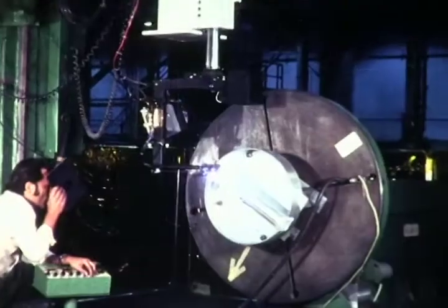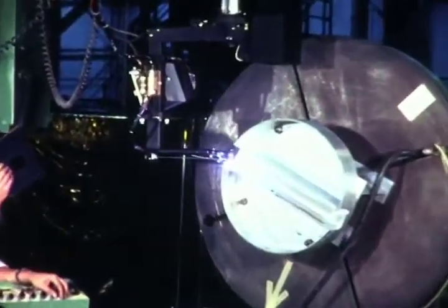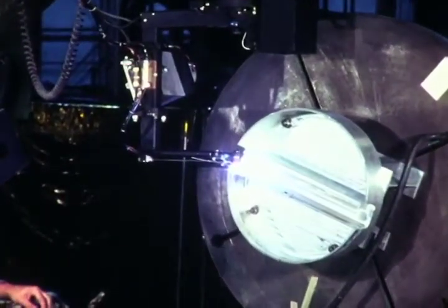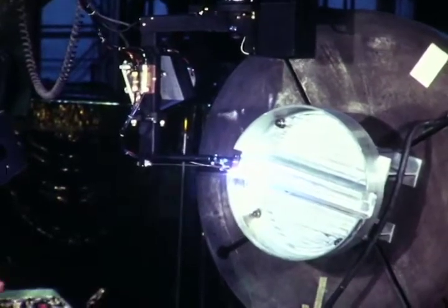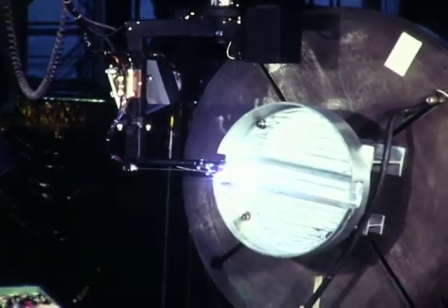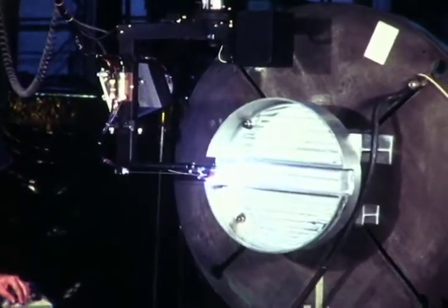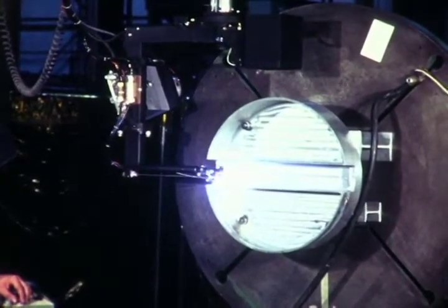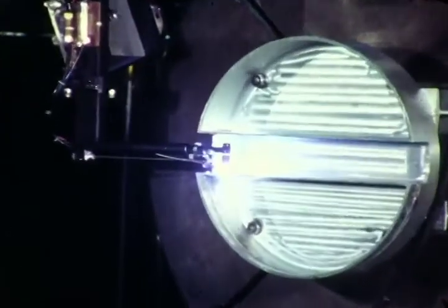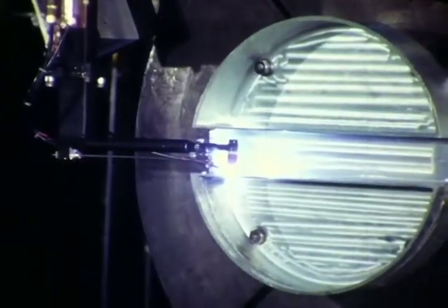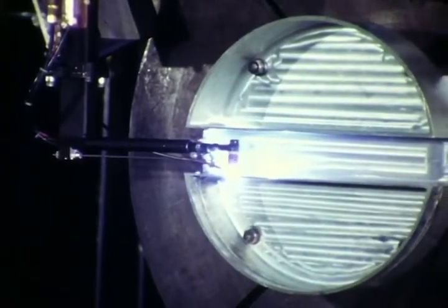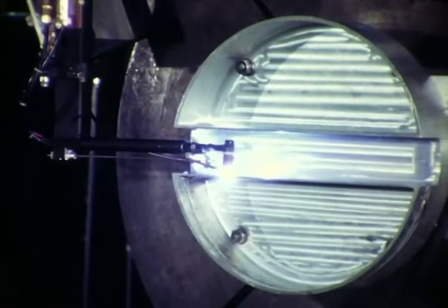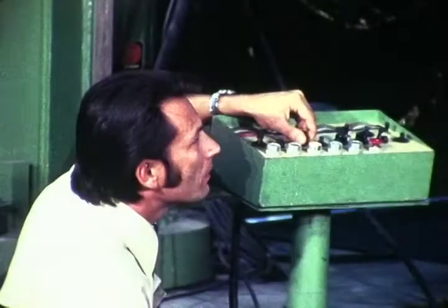A key to obtaining consistent weld penetration and bead contours is the use of a special pre-placed weld backup tape under the weld joint of production assemblies. The self-adhering tape is hand-laid in during fit-up and is simply pulled out after the welding. Prior to welding, the parts have had all dimensions held in the weld joint area to about 10% of nominal.